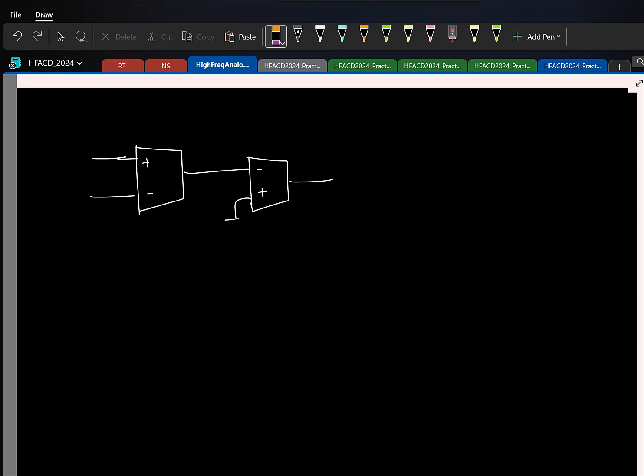If you want to have the exact frequency spectrum, you resort to a simulator, right? Because you don't get any intuition. So we'll only look at low frequency noise. So we'll ignore all the capacitors. So let's say this is GM1, GM2. Now, as you know, this is your 5 transistor OTA. So for the 5 transistor OTA, I already computed the input referred noise voltage for that. We call it like this.